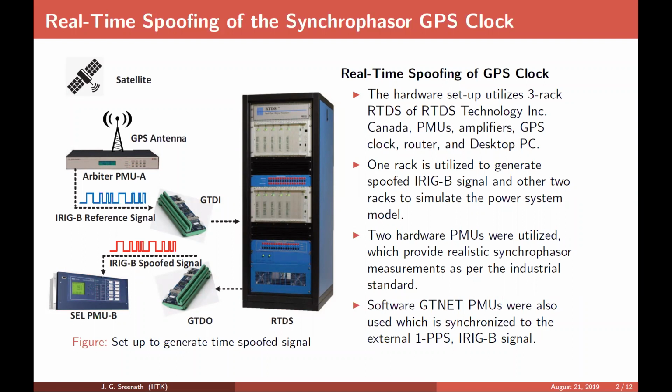So this can be spoofed. What generally happens is that if someone is able to play with this timing information, they can spoof it. This has certain implications in real-life applications as well as in power systems. The normal GPS receiver clocks that you have in your mobile phones or the GPS receivers that you find in various vehicles can be spoofed too, so your navigation can go off track. That is one problem. And when it comes to power systems, as the timing information gets affected, the phase angle measurement gets deviated. It won't report the correct phase angle measurements.